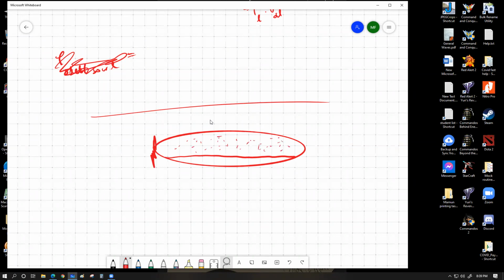The total external volume of the submarine is exactly this much. Within it we can optionally fill this part with water, and this space is filled with various equipment, people, air, everything. The way a submarine is designed, and the way these portions and volumes are made, is such that without any human being inside the submarine, if you fill up the whole thing with water, the total density of the submarine would be more than the density of water. That means if the entire ballast tank is filled up, the total mass of the submarine divided by the total volume of the submarine gives the density of the submarine, which should be somewhat bigger than the density of water, so that the submarine could actually sink down.